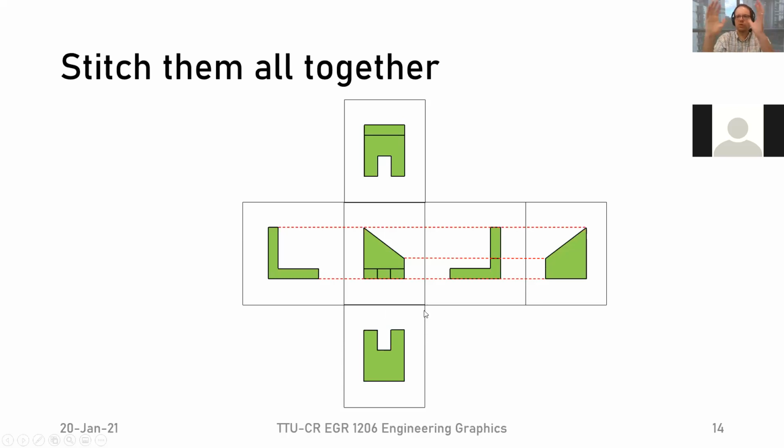Then we'd go back to a box, and that box would then have the front, the 2 sides, the back, and top and bottom. Now, one thing that you can see here is that, of course, if we're unfolding these, then the overall alignment stays the same, right? So the height, if I look at the front of my object and I turn it left or right, then the height that I see here, that height doesn't change.